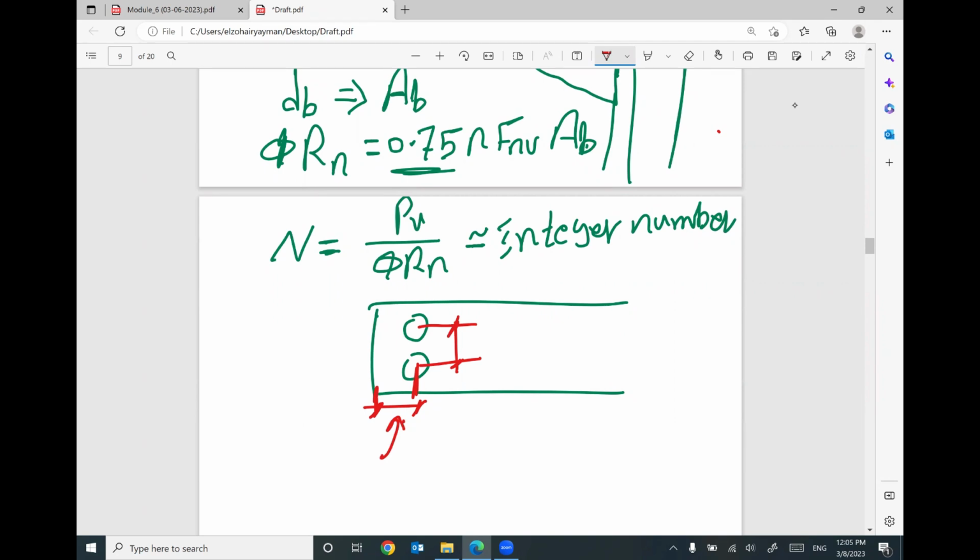The minimum edge distance is based on a table, and this table gives you a value based on the diameter of your bolt. Go back to the last meeting. The minimum spacing between bolts equals 3 times the diameter of the bolt. So if you maintain these requirements or limits, you can select the best arrangement of your bolts.